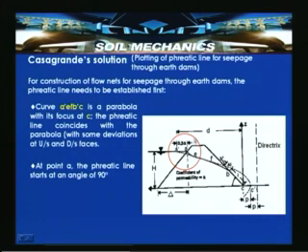In this slide, a dam is shown with a coefficient of permeability K. This distance is 0.3 delta, and this distance is delta. H is the height, the head which is causing the flow, and D is the distance from the vertical axis to this particular point A dash. Here, if A dash E F B dash C is a parabola with its focus at C, the phreatic line coincides with the parabola with some deviations at the upstream and downstream faces.